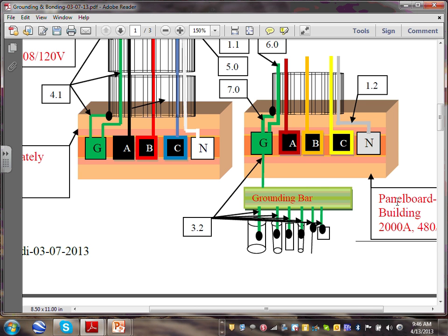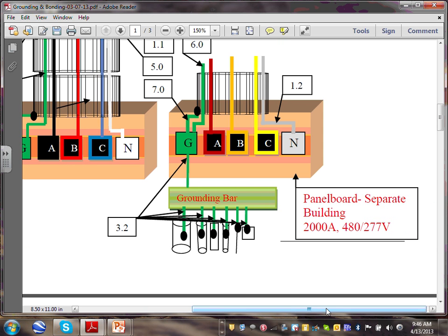So the low voltage satellite dishes and coaxial cables and so forth will be tied to it. I can't emphasize that enough. So the second building is treated as a service in terms of an inter-system bonding terminal. Any comments, guys? Any questions about bonding at the second building?